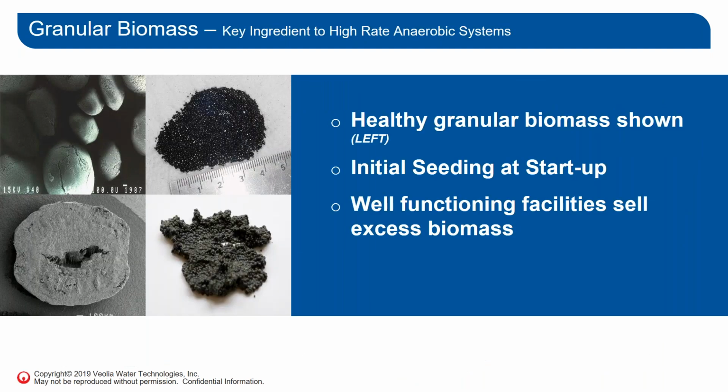So common to these 2 technologies is that they are granular sludge technologies, and on these pictures here you can see what that means. This granular sludge is a black caviar type of sludge, which contains the bacteria and the biomass that will actually convert the COD to biogas. When we start up systems, we introduce this for seeding, which will tremendously speed up the startup and will allow us to get a good performance from the start of the operation.